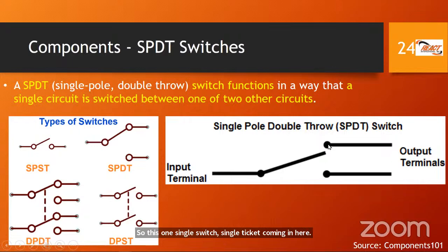So you can either be this one or this one. I'll show a circuit diagram or schematic that will hopefully concretize the use of a single pole double throw switch. The single pole single throw switch is just an on-off switch. The single pole double throw switch allows you to switch between two pathways. So let's look at what that looks like. Hopefully that will make it a little clearer. But the bullet point here is what you need to know for the exam.